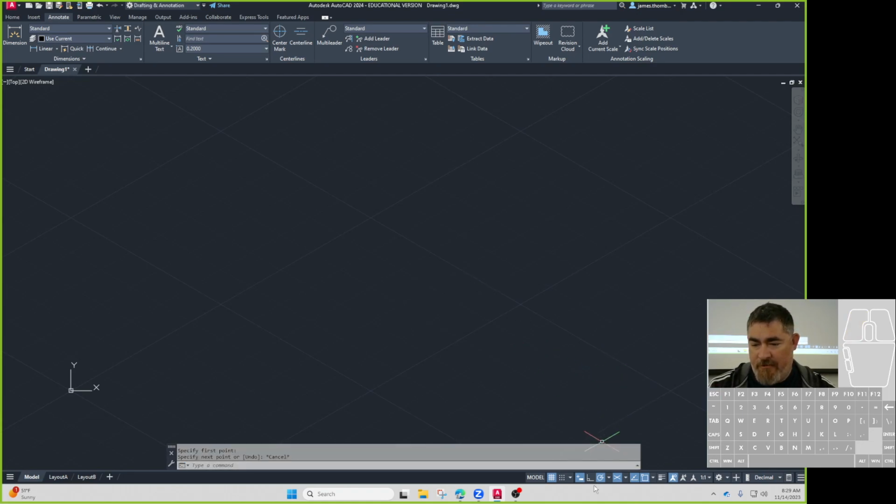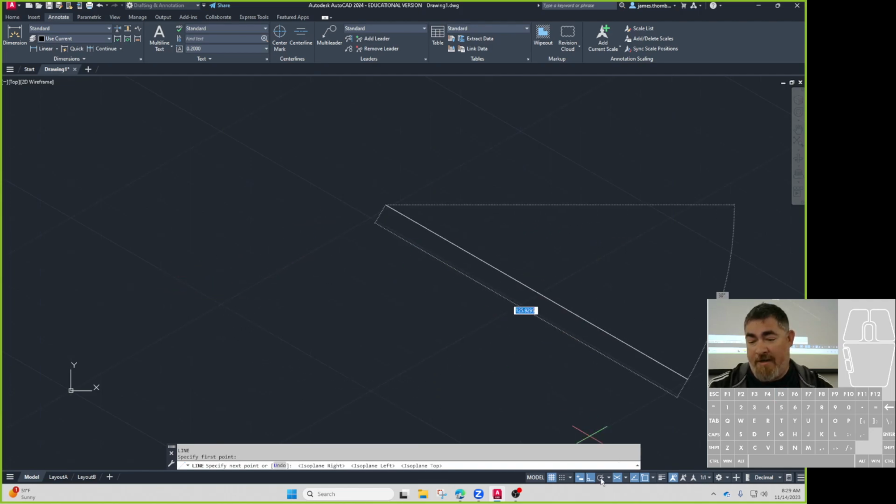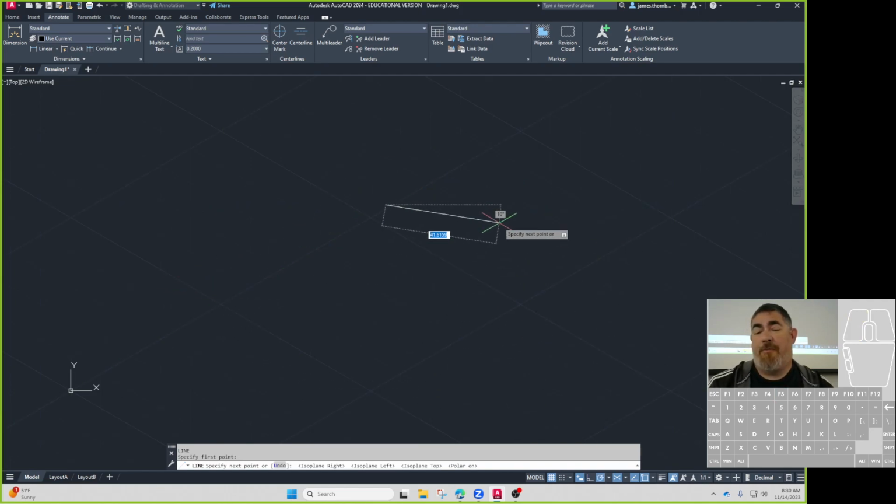If I turn on ortho for some reason, like I want to give myself a heartache, ortho will only go based on the directions of the grid. So you can see there. But polar tracking doesn't care. So since we're already using dynamic mode, polar tracking, I just make sure that it's set at 30, and that when you're drawing, you make sure that you're going with the grid.